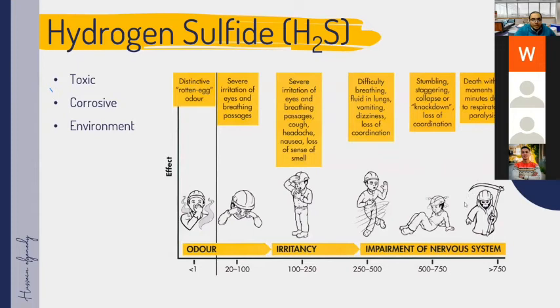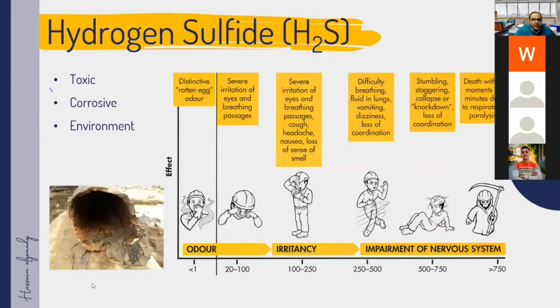ppm, and I am talking about ppm, which is a very small amount, it will be death in a few minutes or moments, depending on the body, the wind, and a lot of other things. But above 750 ppm, it will be a silent killer. That's why, when you deal with a sour gas or a sour gas plant, very tough safety regulations and safety equipment must be used. Okay, this also, as we mentioned, is very corrosive to the pipelines.